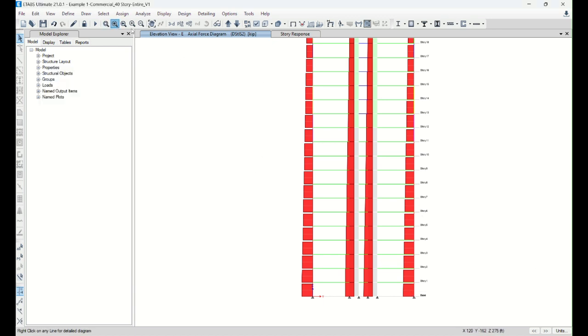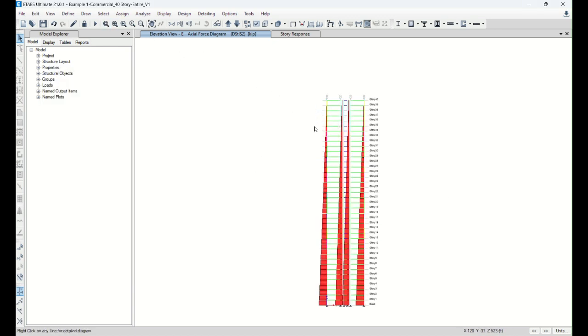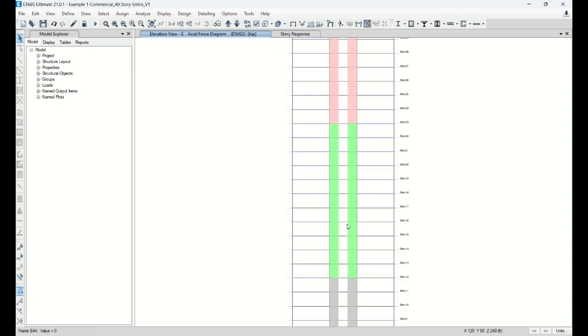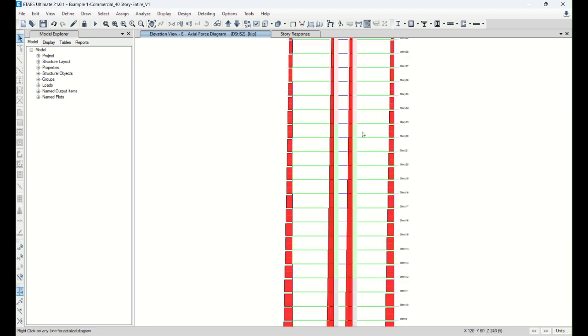But one thing I wanted to make sure, because we're going to add additional stiffness, which is the outrigger, sooner or later. But in this initial model, there is no big horizontal deep beam member or truss between the wall and the column. So all the floor loads, which are dead load, self-weight, superimposed dead load, and live load, are coming down through the column.